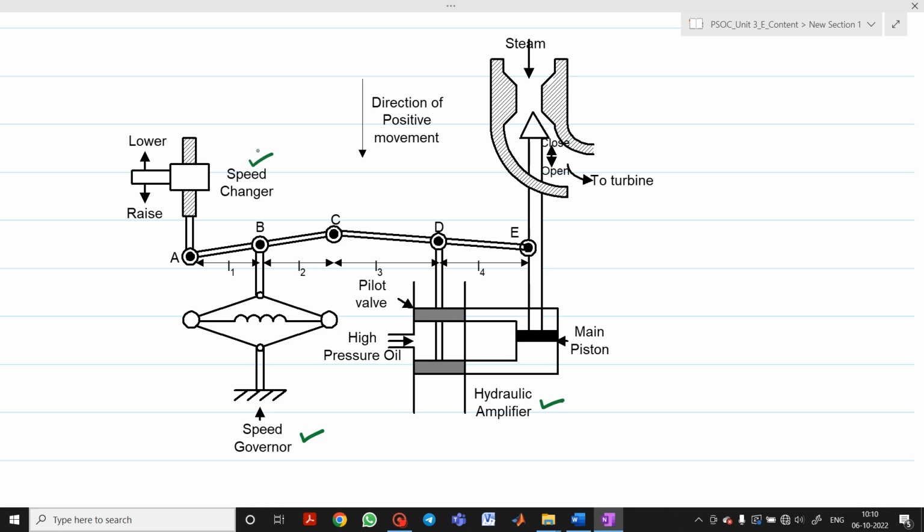In a modern and large interconnected system, manual regulation is not feasible, and hence automatic generation and voltage regulation equipment is installed on each generator. So this figure gives a schematic diagram of a load frequency and excitation voltage regulators of the turbo generator.